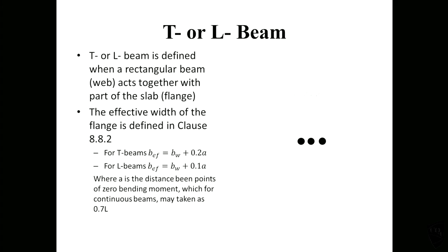So when you have L or T beams, clause 8.8.2 defines the effective width.